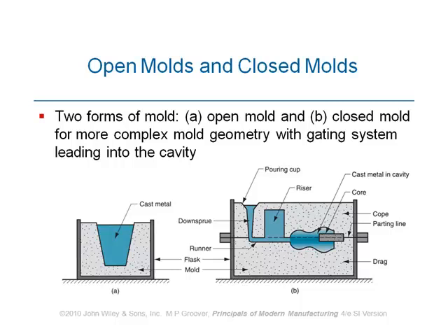Okay? And when outside is taking shape, that shape remains in place to the end of the process, the outside boundary. Meaning that just the skin of the part or cavity has been solidified. However, material inside is still in molten state. And over time, after some time, inside of the material will also solidify.